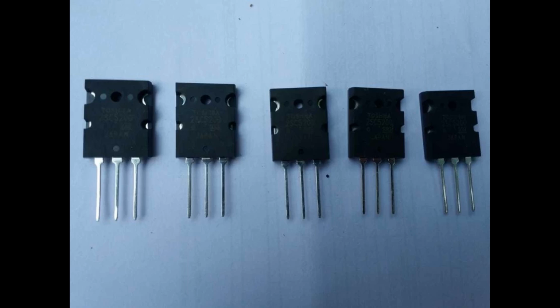Switching voltage regulators, also known as switch-mode power supplies, use transistors, typically MOSFETs, to efficiently regulate the output voltage. Here's how they work. Pulse width modulation, PWM: the input voltage is rapidly switched on and off using a PWM control circuit. When the transistor, usually an N-channel MOSFET, is on, the energy is stored in an inductor, and when it's off, the energy is transferred to the output.